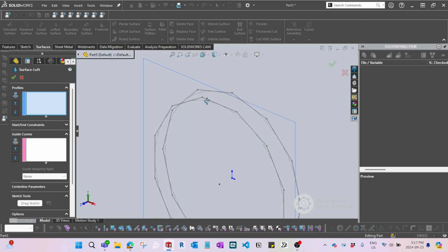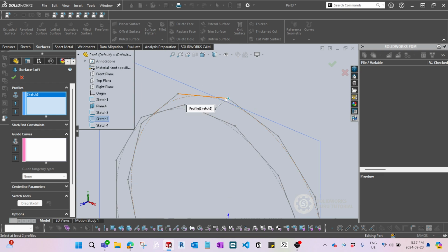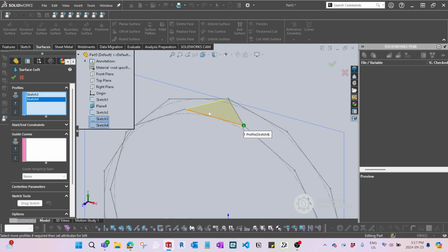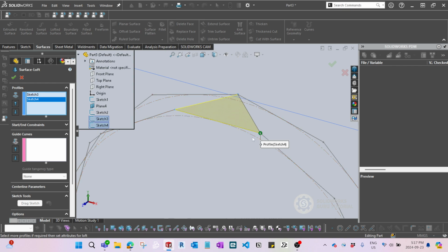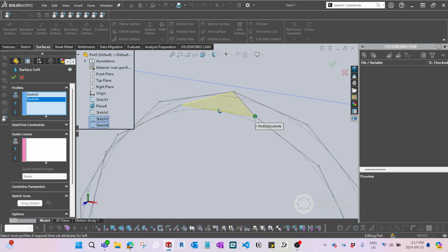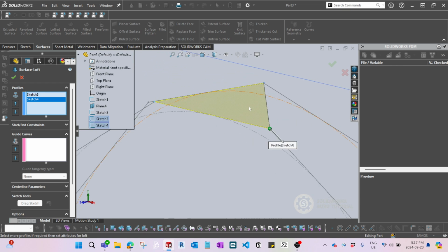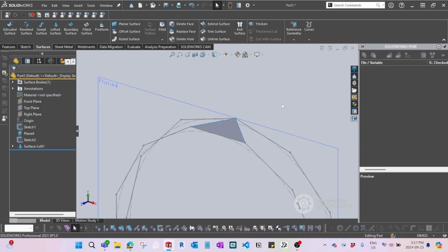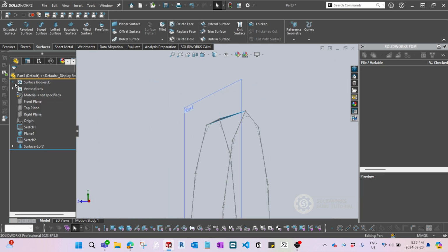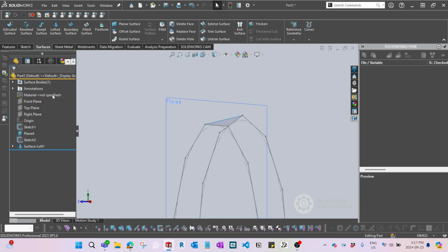This is the time we're going to use the loft that we never used before. What loft does is, once you click the points, I'm just going to select 4, and that's going to connect 8 pieces and create triangular pieces, okay? Just hit OK, and as you can see, this is not showing as a solid body.